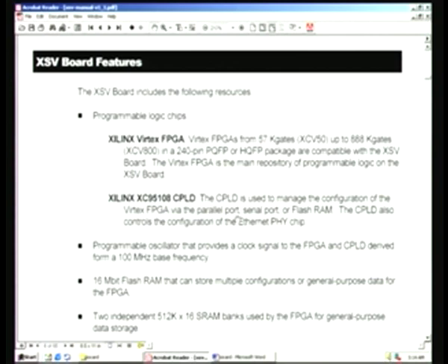There is also a parallel port on the board, which can be connected to the parallel port of standard computers, say personal computers such as Pentium, as LPT1 or LPT2. There is a provision for selecting whichever you want. It also has a serial port, through which RS-232 type of communication can be undertaken, and for any of your applications you can use this, or you can even download the bit stream through the serial port, but it is going to be time consuming. It is preferable that we take the parallel port, and this is what we are going to adopt.